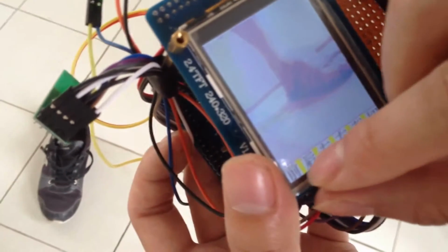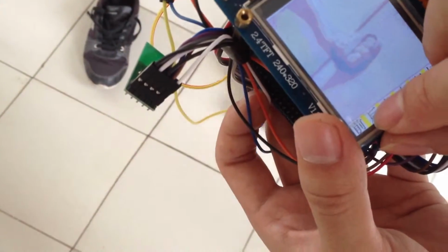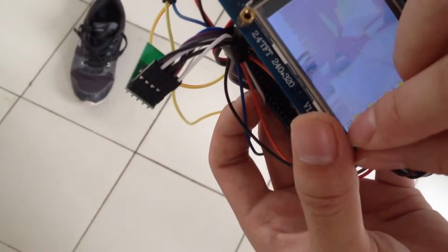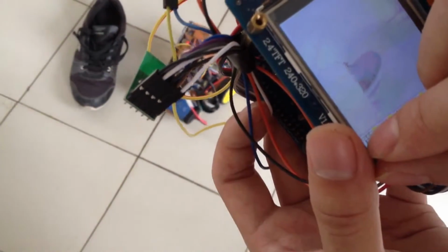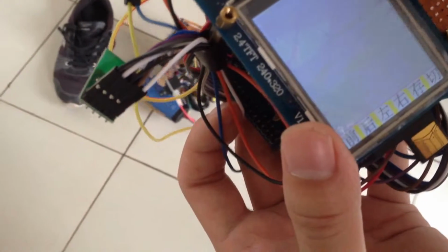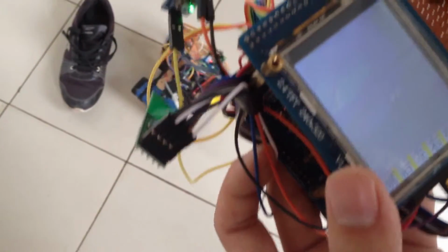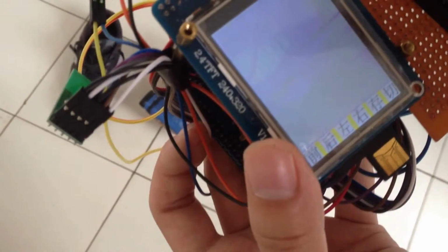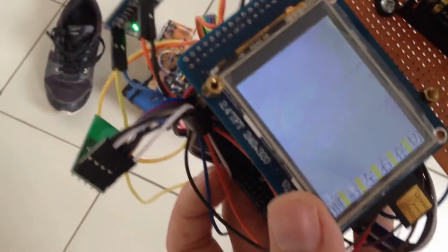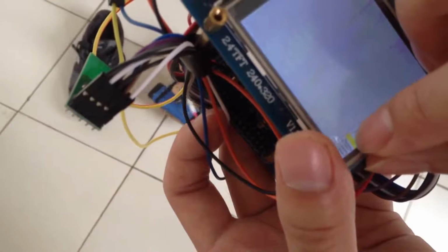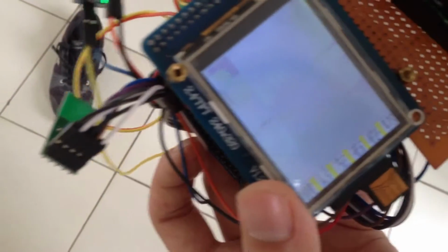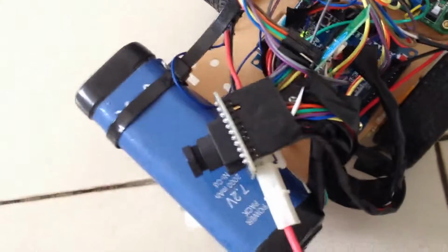And about the data transmission in this project, only the function of the wireless chip is not enough because some pictures will lose data. So I added different kinds of acknowledgement flags and rules to build correct communication between sender and receiver. I also designed the algorithm so that the car can send video and receive commands to move at the same time, using only a half-duplex wireless chip.